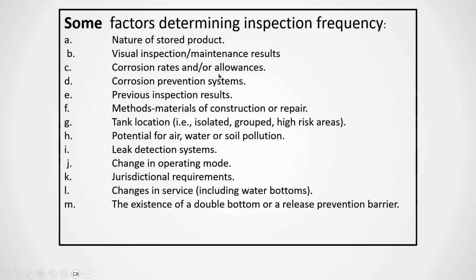Corrosion rates: if a corrosive liquid or corrosive environment is there, then what is the corrosion rate? Last year the thickness was like this, this year the thickness is like this, so you can calculate the thickness reduction. Then as per the thickness reduction, you can decide the frequency of the testing.